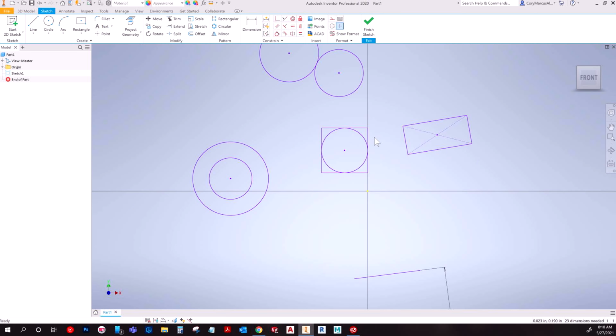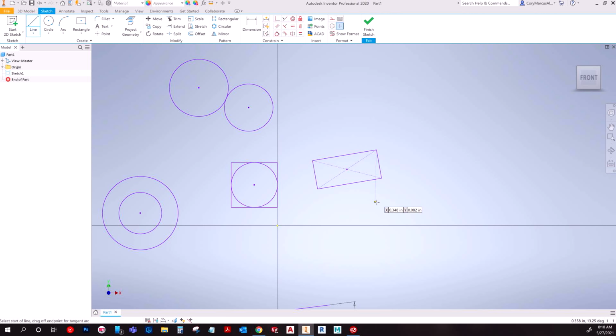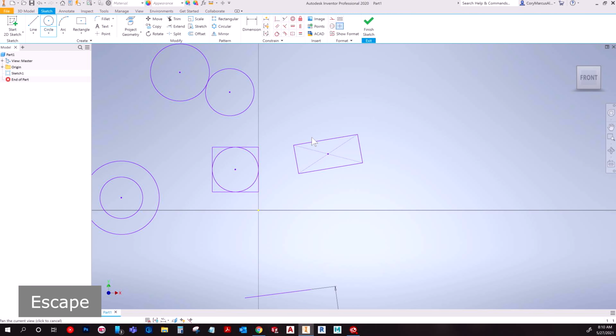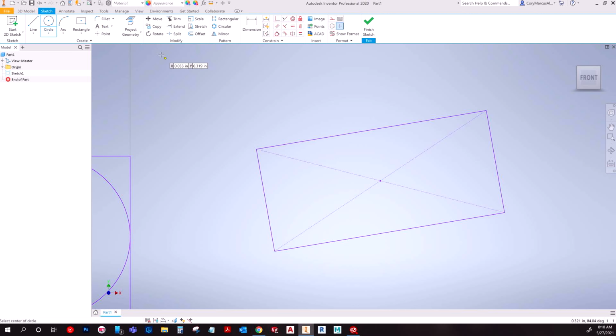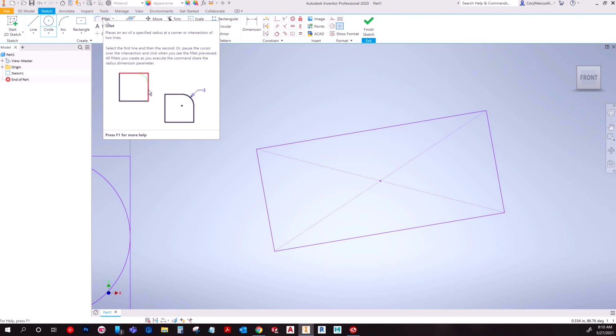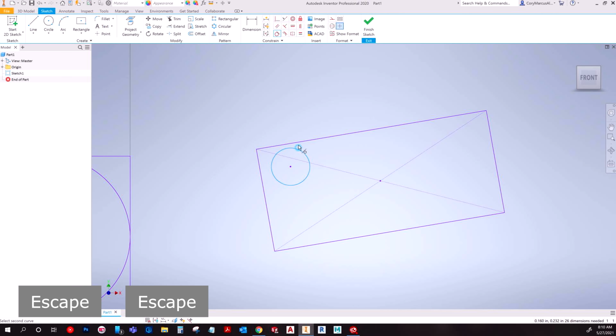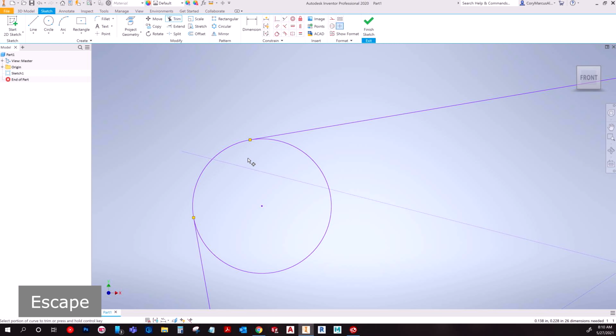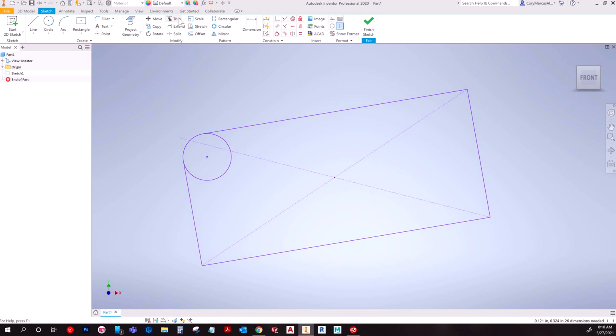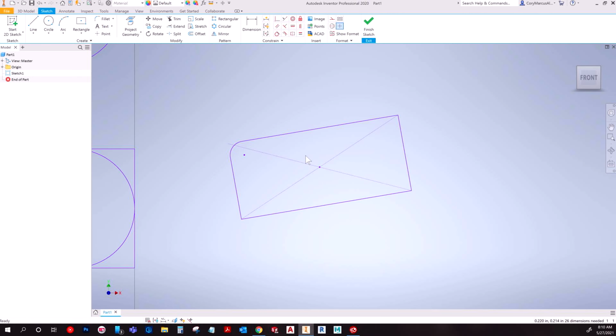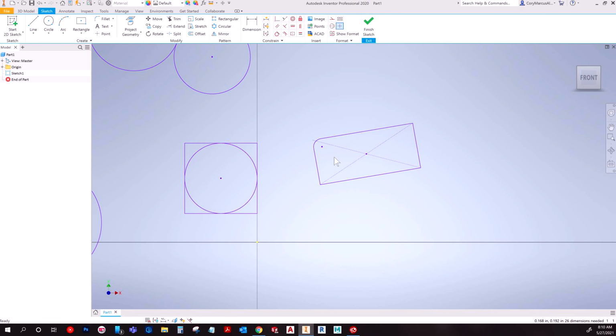But tangent's really straightforward. Basically, you're probably going to be making a fillet if you're using a tangent. And I'm kind of willy-nilly about using actual fillet commands. They work, a lot of the times they work as intended just fine, but I tend to always just use a circle and then manually constrain it and trim it personally. This is my typical routine right here. Now granted, it's a little different when you got this geometry here, but the same concept still applies. Basically you just draw it in, trim it, and there's your round, just like that. I guess that's really about it for that one.